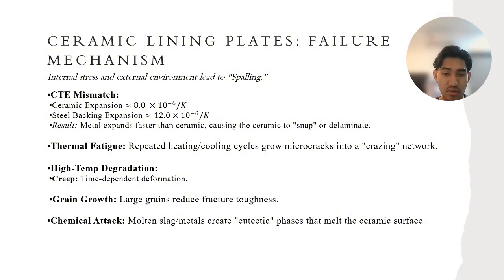So the thermal fatigue: repeated heating and cooling cycles grow microcracks into a crazed network. High temperature degradation: creep, time-dependent deformation, and grain growth, where large grains reduce fracture toughness. Chemical attack: molten slag or metals create eutectic phases that melt the ceramic surfaces.